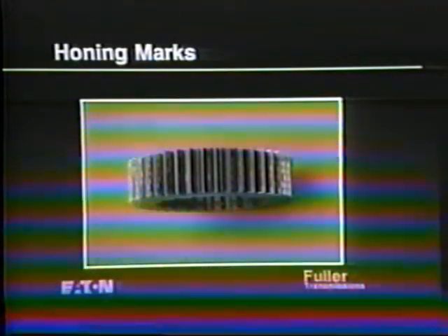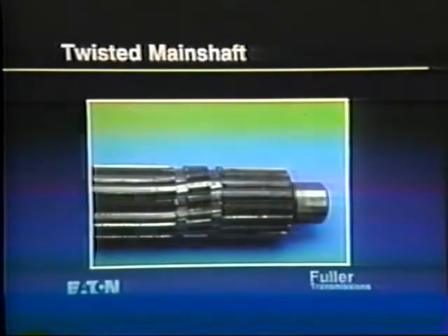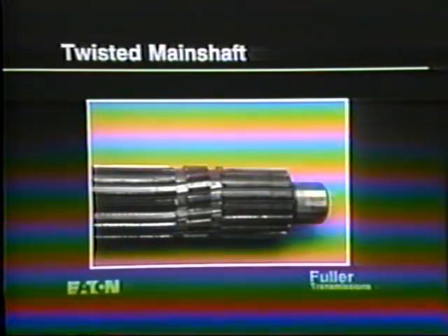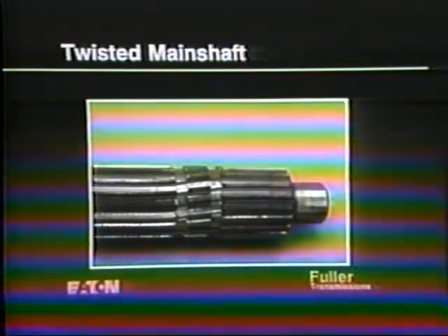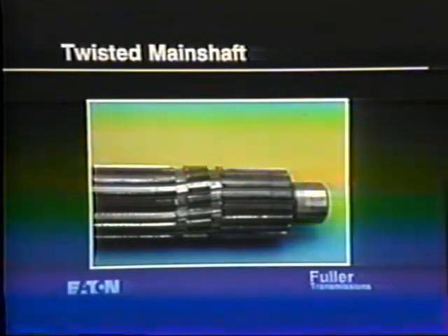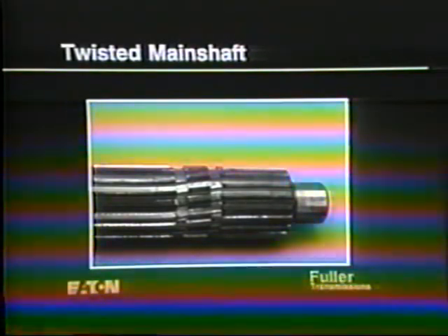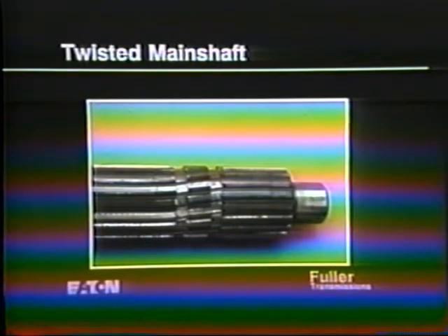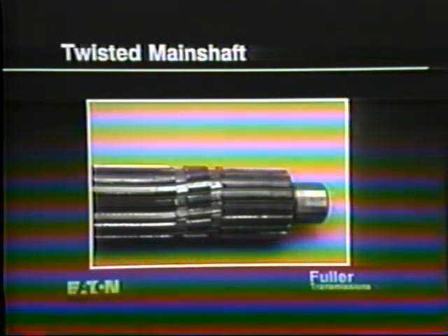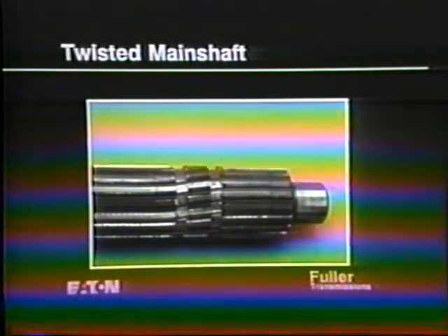is honed smooth. When too much torque or not enough reduction is imposed on transmission shafts, failures result in the form of twists or even fractures. Twisted main shafts will cause the sliding clutches to bind on the crooked shaft splines, resulting in hard or impossible shifting.